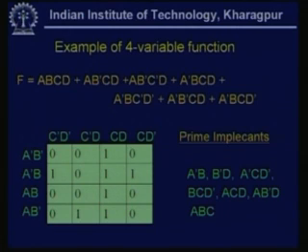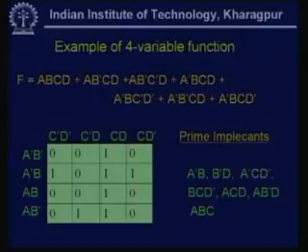Now, as already we have seen that there are many ones that are already included in more than one group, that can be a quad or that can be a couple. So, there can be many redundant things. So, all these are prime implicants because they represent one group. Now, these are not all necessary for the function, because many are redundant, that one exists in more than one group. So, these are not all necessary.